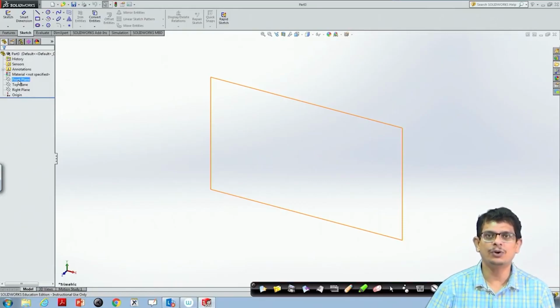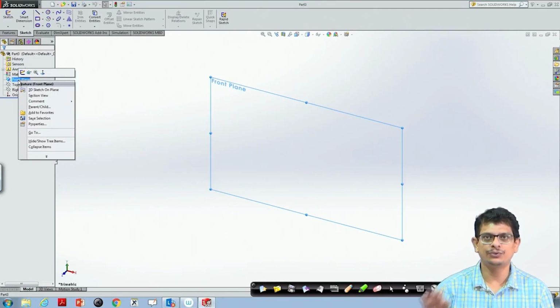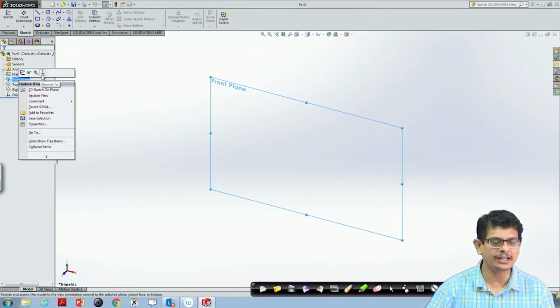So, the first thing we are going to do is pick the front plane. Pick means just move your mouse, then give a right click of that button. On the mouse, there are two buttons, right side and left side, and pick the right side button. Once you click that, with a single click, it opens a dialog box asking, would you like to draw normal to that plane?